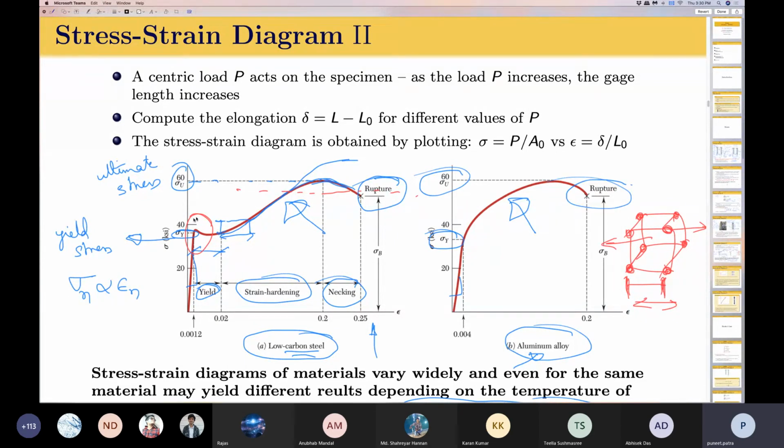New slip planes are being created here. These new slip planes cause a rearrangement of atomic positions, and therefore all kinds of forces start to act, and in the engineering stress strain diagram you observe a dip. Okay, I'm not sure whether this will be very clear to you because this is a bit advanced concept, but bear with me for the moment.